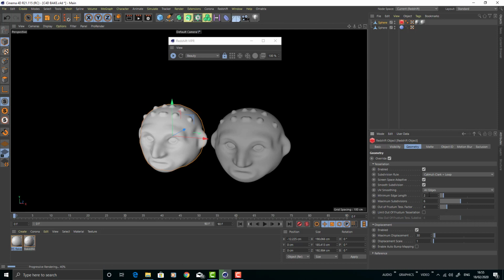So typically when this is set at 4, this is when it's going to try to convince you that it can do the rest with the automatic bump mapping. The automatic bump mapping can certainly add some nice details, but I wouldn't use it on low resolution meshes with medium to low resolution texture maps. Typically I would normally leave this turned on when I'm doing a proper sculpt, because it's normally high frequency detail which is going to be pushed through. But you can see here with the minimum edge length put down to 2, it's done a pretty nice job of it overall.